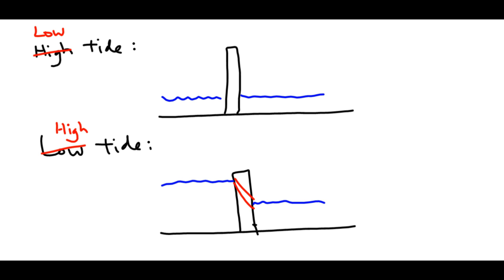Okay, so we put a little channel between the two ends, the two sides. We flow water through. The water loses gravitational potential energy, which is converted to kinetic energy. The water's kinetic energy turns a turbine, which powers a generator. And this is how tidal power works. So we use the tides to generate a difference in height between two sides of a wall, and from that difference in height, we drive a turbine as the higher water loses its gravitational potential energy, and that's our process.